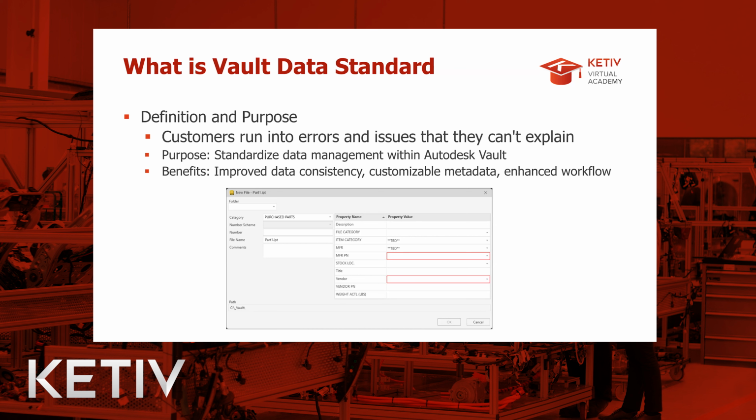One of the examples I use a lot is from when I was doing Vault administration. I would have users grabbing models from, let's say, McMaster-Carr. But since the vendor field was just an open field, I'd have McMaster-Carr spelled 15, 16, 17 different ways. Some MC Carr, some MC dash Carr, McMaster dash Carr, all of that fun stuff. By utilizing Data Standard, you can have a pick list available so that the user selects common vendors, so that you maintain that common vendor name when you're analyzing or sorting through your data.